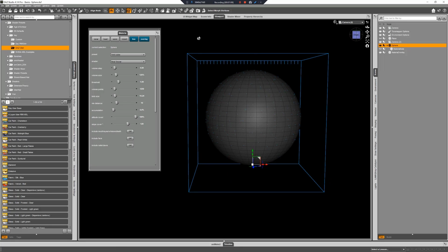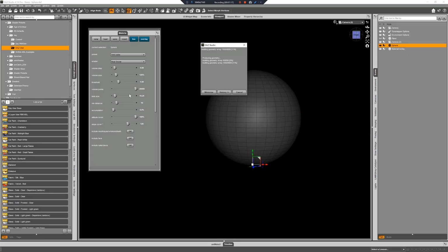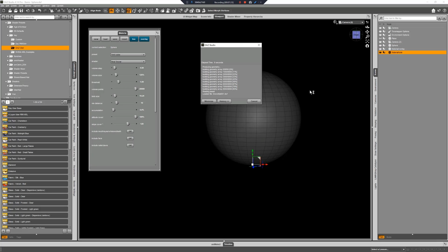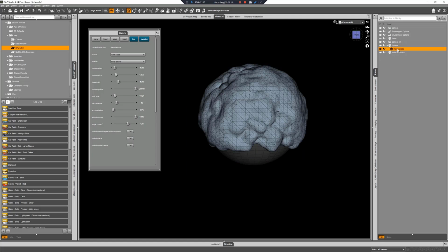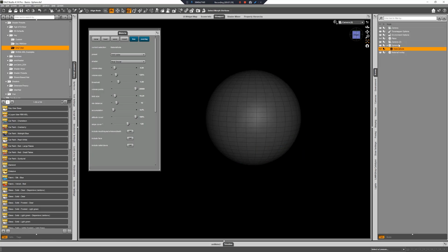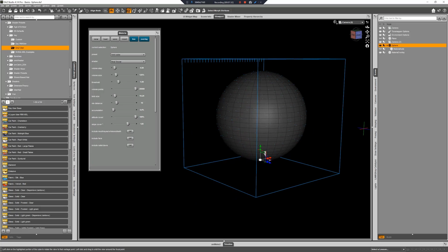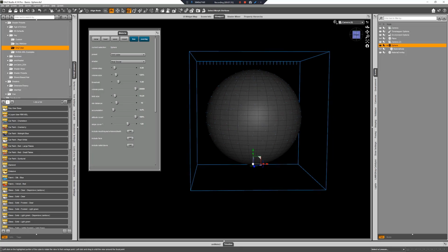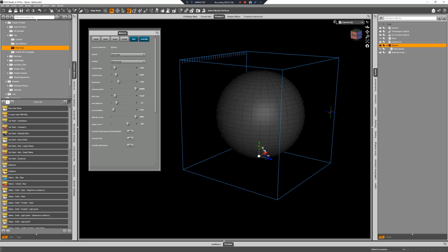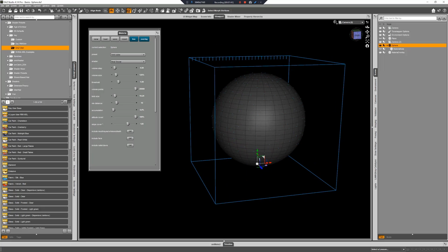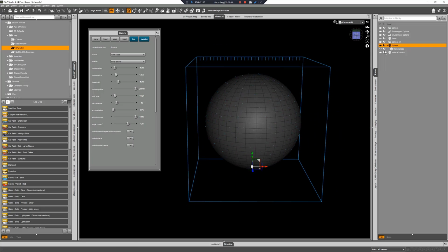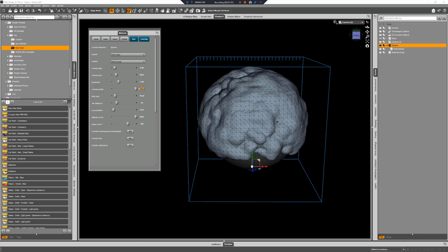Alright, so volume points are obviously an important setting. There is no need to use an incredible amount of points, because Materia is going to discard and disregard some of these points. Basically only the particle points matching some conditions will actually be included in the simulation. In fact, you see that now we asked for 20,000 points, but probably we got no more than 200 or 300. There are just a few, because that's what is necessary to produce a consistent geometry.